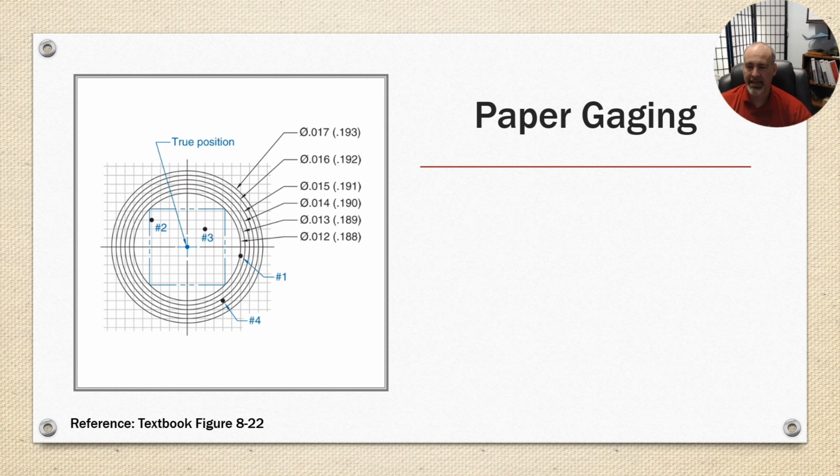So in this example in the graphic on the left, you have a 188 thousandths diameter hole at maximum material condition, and its tolerance must be, let's see, 1, 2, 3, 4, 5, plus or minus 5 on the diameter. So if you're going to use this method, you would need to take into account how many rings.